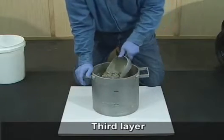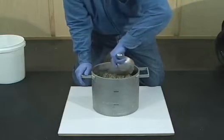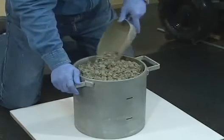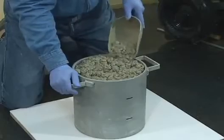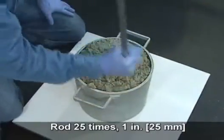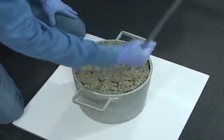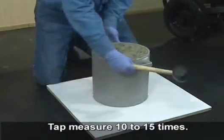Add the third layer of concrete to the measure. Rod the layer 25 times. The rod should penetrate through the third layer and into the second layer about 1 inch. Tap the exterior of the measure 10 to 15 times with the mallet.